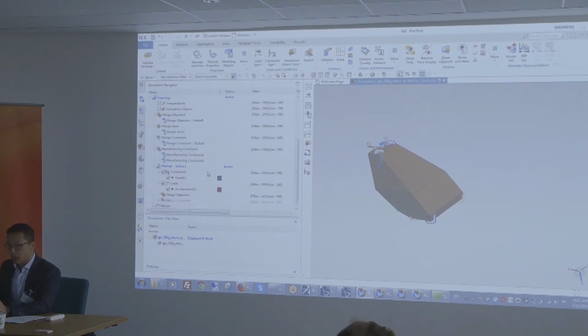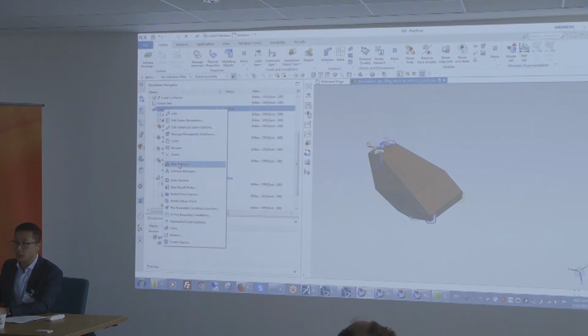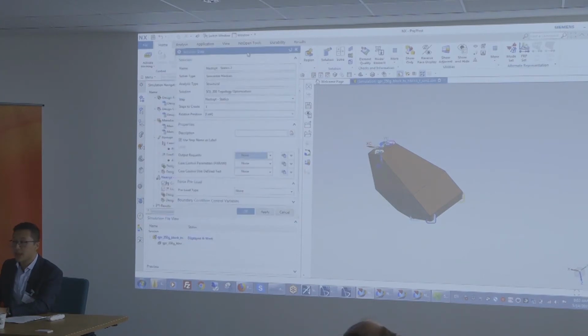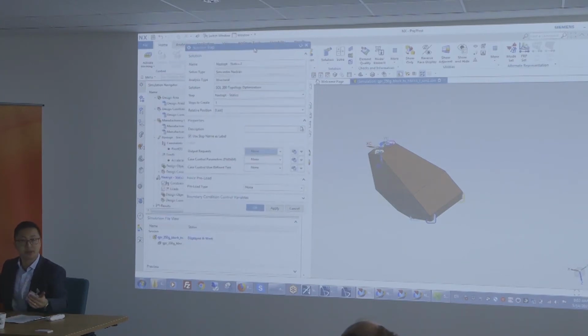Right? Now before I run it, let me just go ahead and look at the different subcases we can put. Right? So we're minimizing the compliance for all of the subcases, and those subcases can be statics, a direct frequency, if you have kind of an impulse, or a PSD that you can convert into the time domain.